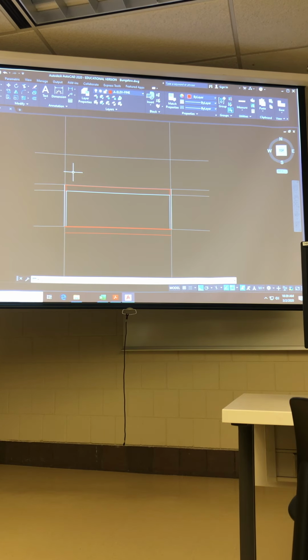Now, I can go ahead from here and figure out where this diagonal web member is. Piece of cake, because what I'm actually gonna do is just start with this corner where my vertical web member hits the bottom chord of the truss. And I'm gonna draw that line perpendicular to my top chord. Oops, that wasn't perpendicular.